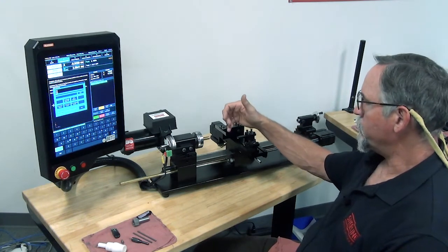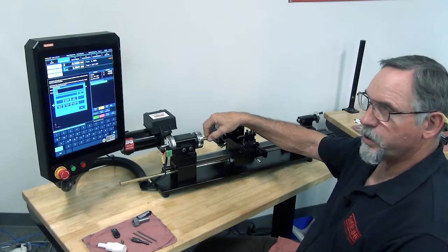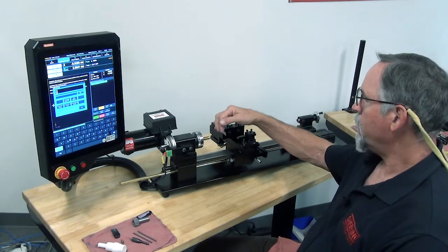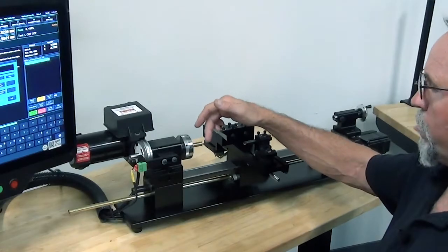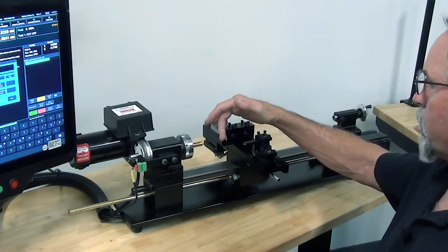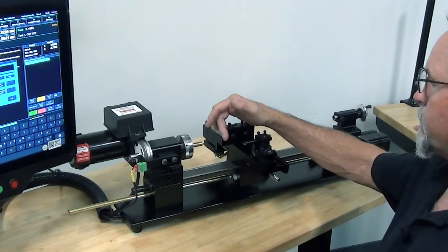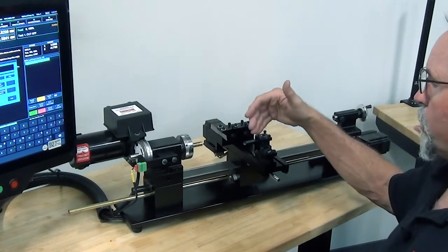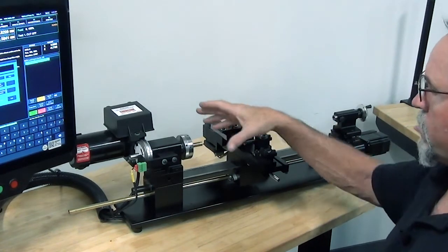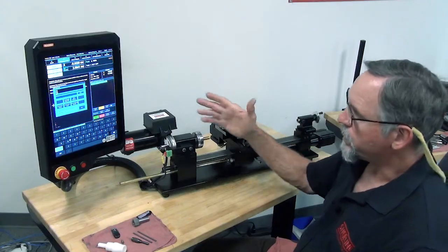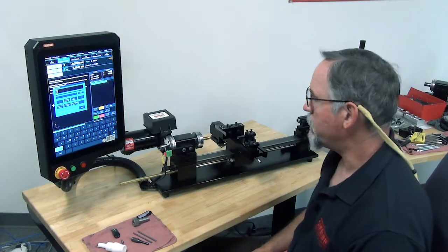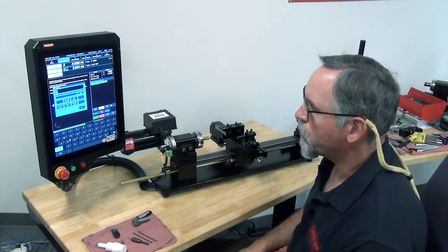If you want to speed up your part, if you're doing production or multiple parts, and you don't want to have all this movement, then you're going to have to actually put in your program how far this is going to move on the Z axis and away in the X axis before you call up the next tool. And you can cut down the rapid travel distance of your tools. But using the park position is a pretty easy way to get yourself to a clearance point.